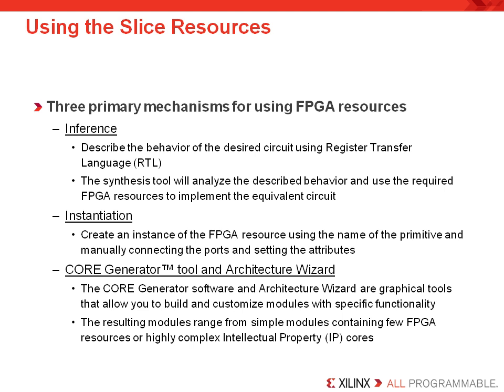The core generator and the architecture wizard make larger optimized components available to you. While some cores have a charge associated with them, most do not have a charge associated with them. The cores range from simple components to large, highly complex IP. The architecture wizard, frankly, is most commonly used for creation of custom PLL and DCM components.